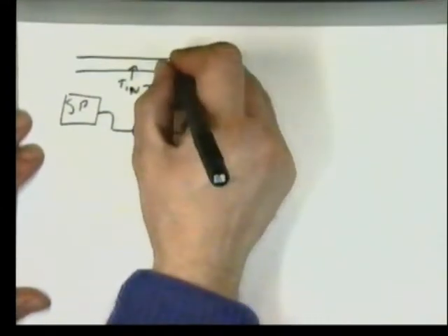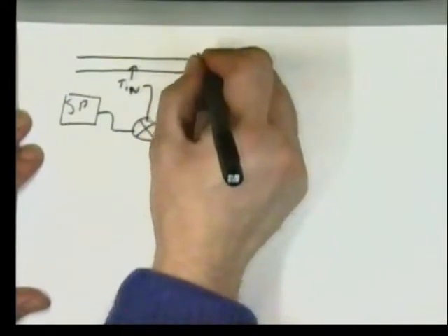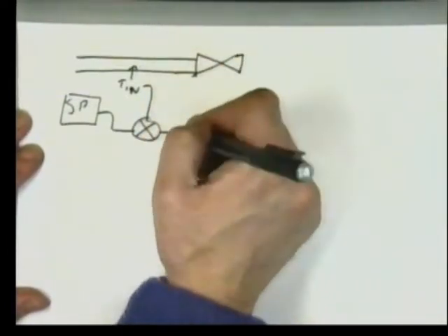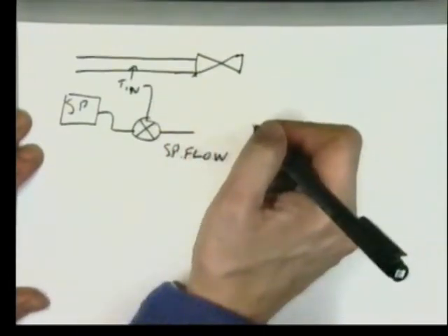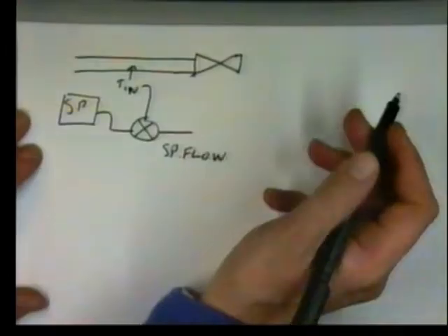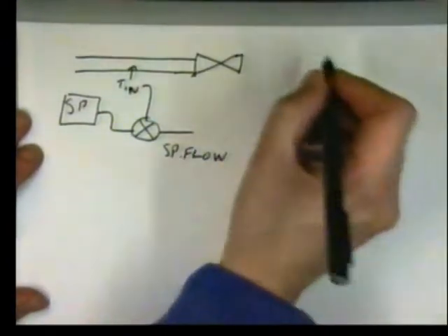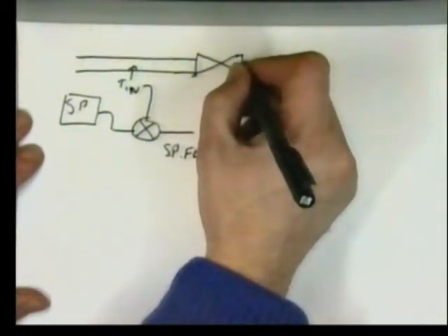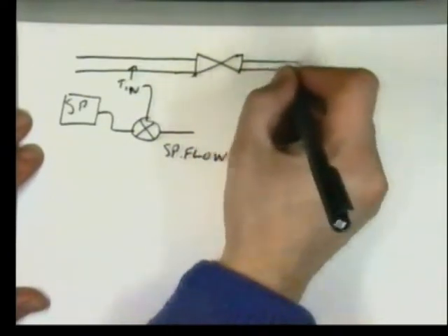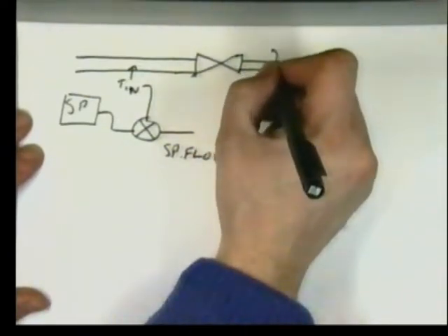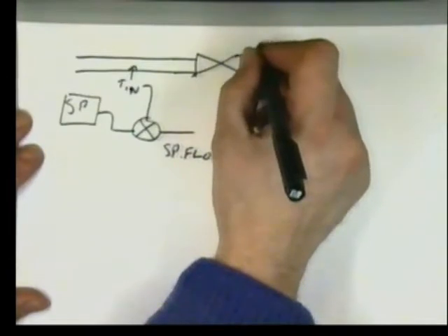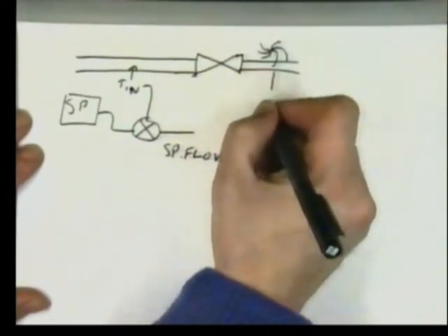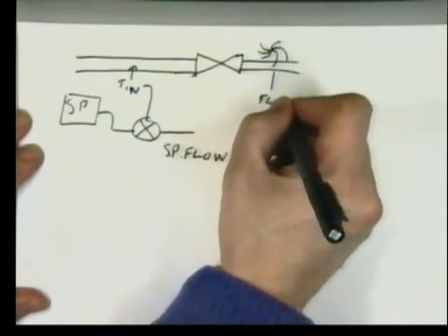Now, if you remember, I showed you, when I opened the shower system up, that valve, because that valve was the simple solenoid that moved backwards and forwards and let water flow in the pipe. But we need to measure how much water is flowing as well. So hopefully you might remember that also fitted to this system was a very simple turbine meter. What this gave us was a measure of the flow rate.